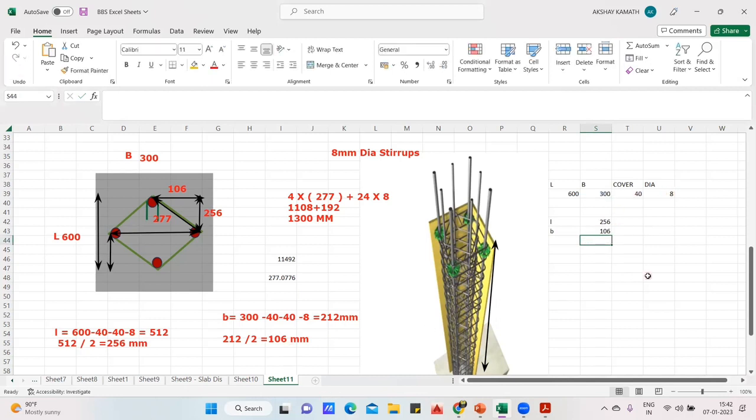Now next you have to find the cutting length. First, the Pythagoras value, which I'll name C. The formula is plus SQRT, square root of 2 times open bracket, click on this, close the bracket, use the shift key on the keyboard with the symbol on number 6 to make it square, plus again open the bracket, click on this, close the bracket, use this symbol, say 2, and close the bracket.